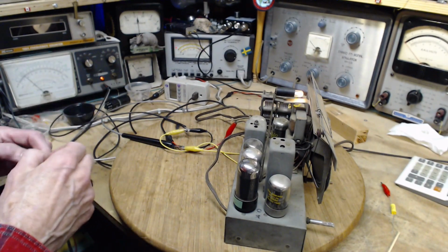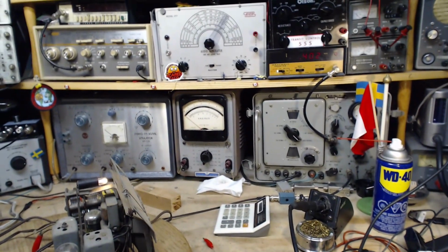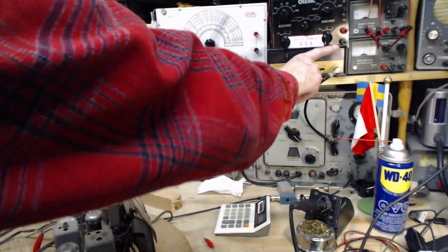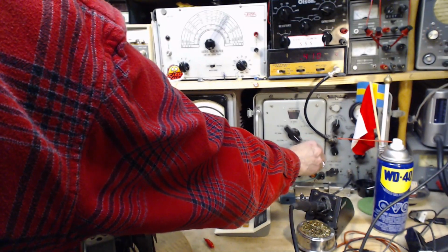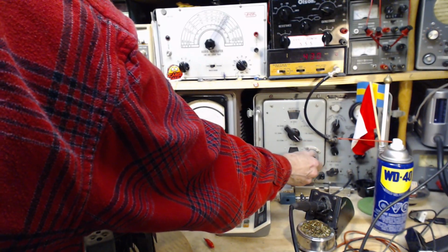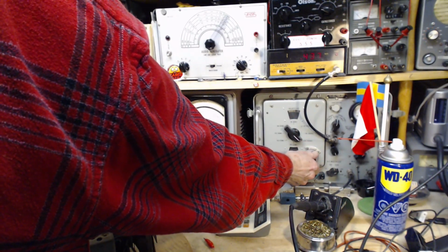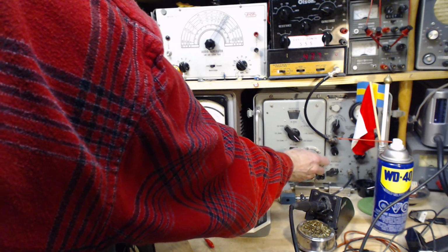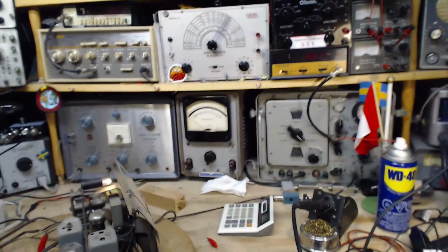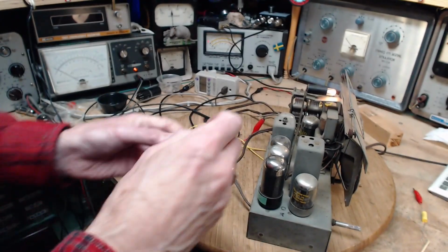Well, let's just start moving it to 455. We'll see what happens as I try to do this. So I'm going to take this up until we can't hear it, way up here. Okay, and now I'm just going to try to make adjustments to make that stronger so we can hear it again. Don't really worry about the meter right now.